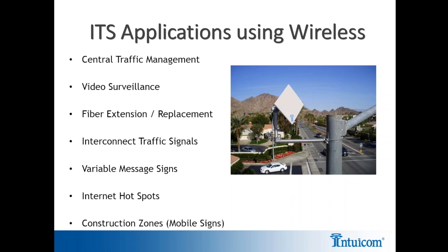Most cities today have a mixture of communication media that interconnect their traffic controllers, and it is important to know that wireless can be added to any other type of communication system, including copper wire, FSK, base, closed loop, and central systems. Also, in the case of having any legacy equipment, wireless networks continue to deliver amazing return on investment for legacy systems using RS-232 serial communications protocol.